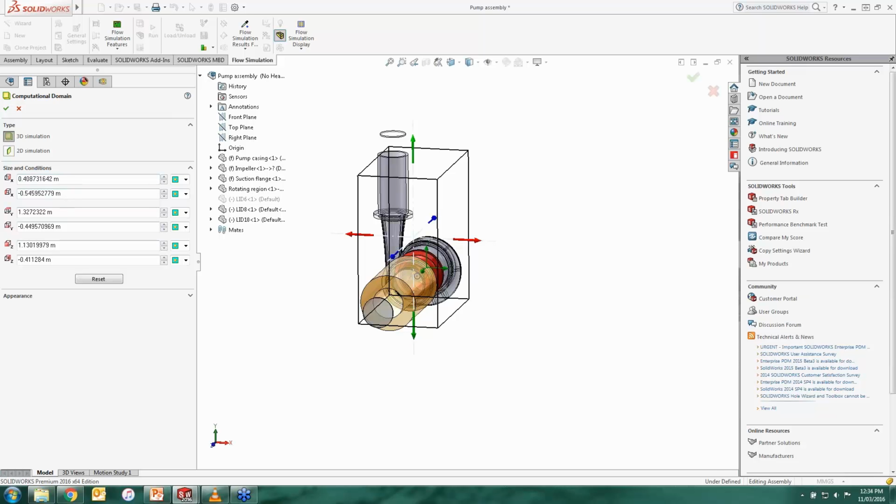Also, you do have the option to go for a symmetrical boundary condition, means there is exactly the same shape on the left side, right side, upside or downside in any direction, or you're saying there is something going to be repeated, periodicity, and simply telling, all right, I have an impeller with 10 blades, and basically it's fully symmetrical, but what I would like to do, solve it for one and expand it to the other 10 and make a fully symmetrical result.